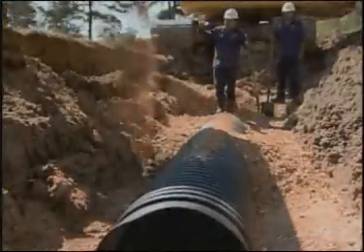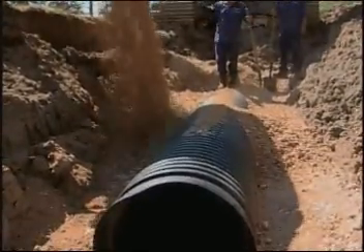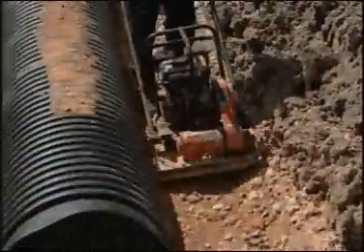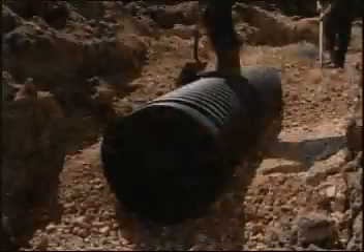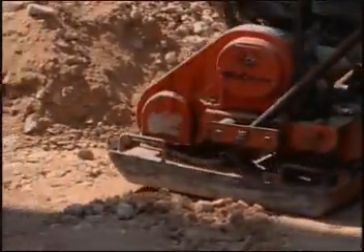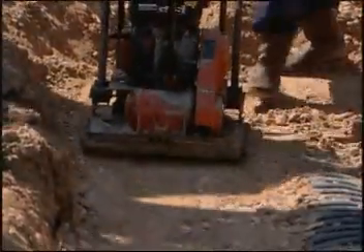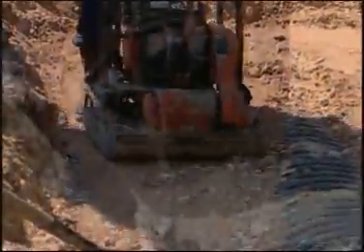Another point to remember is that you can't just dump and slice in the placement of embedment materials when installing flexible pipe. More labor time is needed for installation of that product. To make sure the embedment material is placed and compacted properly, the contractor may be required to limit lift thicknesses to 6 to 8 inches to achieve the required density. He may also use more equipment, either the pogo stick type compactor for sands and fine gravels, or the vibratory plate compactor for coarse gravel or crushed rock.